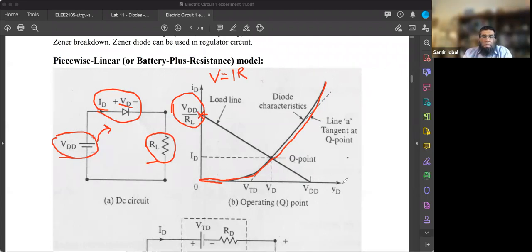And on the x-axis, we have the voltage. So we have a point of what is the maximum voltage that can pass through the whole circuit. So we get 2 points, and if we connect those points, we get what we call a load line. So the load line tells us that the current can stay only on this value throughout the operation.